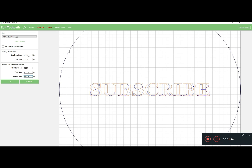The depth per pass. So we're only going to take one pass because it is a V-bit. It's not that big of a deal. It's going to come in, it's going to swoop, but you can take 2 passes. You can maybe cut this in half, divide the 1/4 inch by 2, and then it would take 2 passes. But I think we're fine with just one. So we're just going to hit OK.